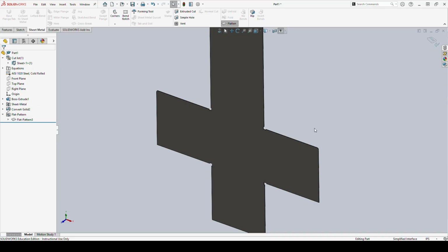And this is important because when we actually create our drawings and everything for our sheet metal pieces, we really do want to have some form of flat pattern, whether that is so that we can dimension and add dimensions and other things to it, or so we can send this to the water jet to get cut out like this, because this is the piece and this is the shape that's going to get water jet and cut out.